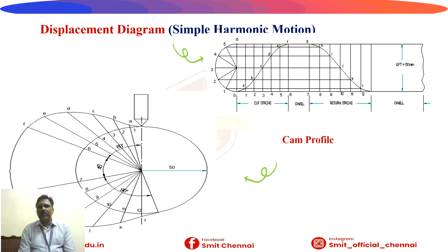Then finally, you will get a cam profile diagram. We have to use a freehand sketch only. We should not join it with the scale. Just use the pencil and take a fine path, joining all the points. It will clearly give a cam profile. Then finally, you have to dot the curve, followed by the cam radius. That is the circular one, which we already took as 50 mm.